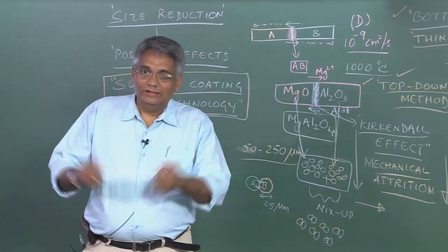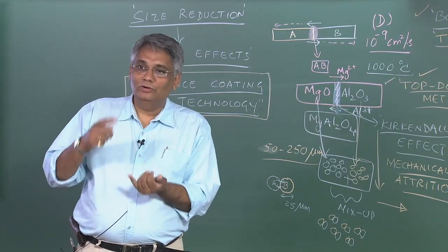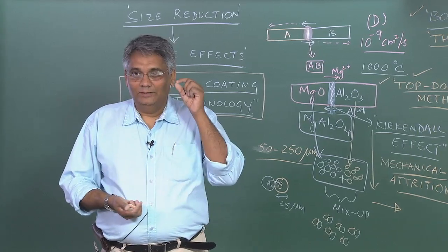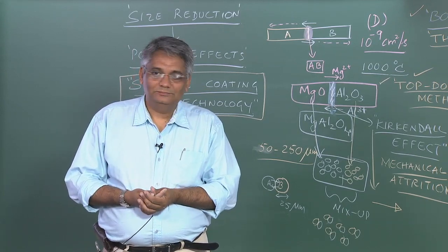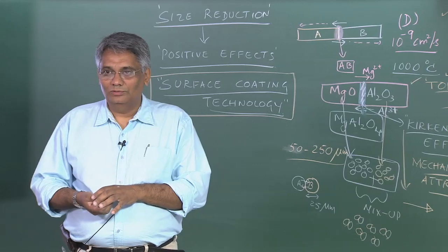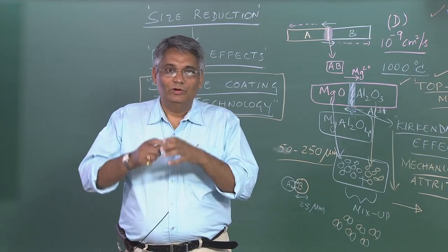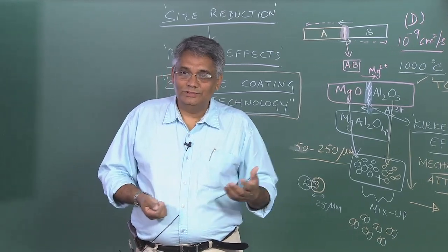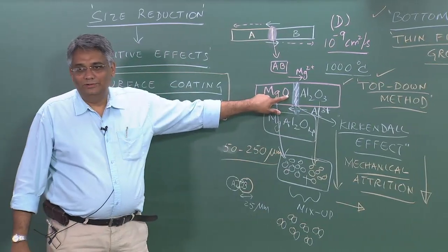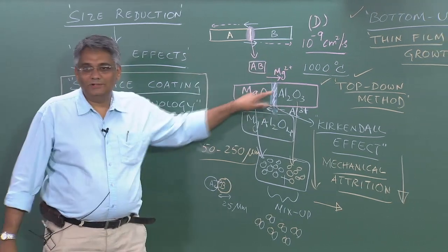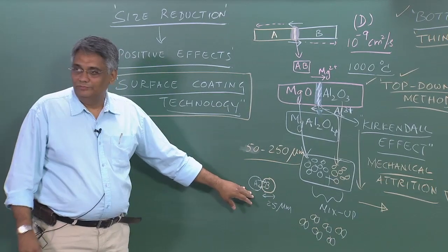So reaction between individual atoms or small clusters, you're looking at the diffusion process in bulk, surface, and between grain boundaries. So in which case are the grain boundaries more? Again, I come back to that and try to impress upon the fact that if you have a large number of grain boundaries, the diffusion is much faster. Obviously here, there's only one boundary that separates these two compounds, and I have increased the number of grain boundaries here. See what happens in the process of diffusion.